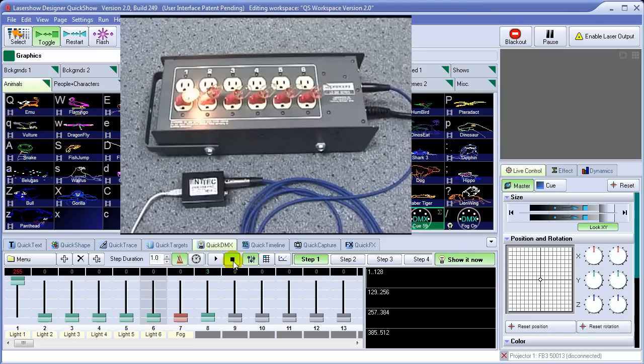Certain lighting fixtures have control channels. These are channels that will turn the light on and turn the fixture off and reset various parameters. For those kind of operations, you definitely would not want to use the smooth change, and that's why we have this stepped change operation. So for certain channels, when you want to go immediately right to a value on a step, we'll just do that.